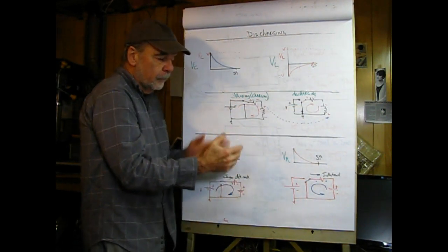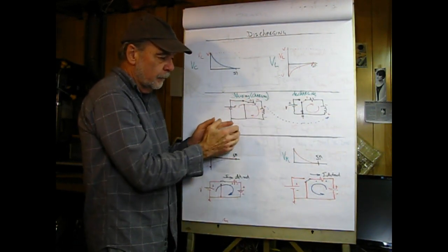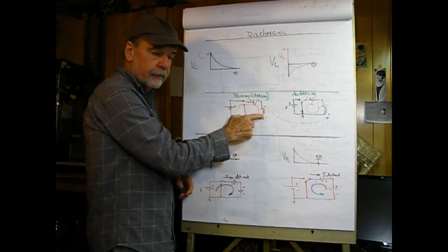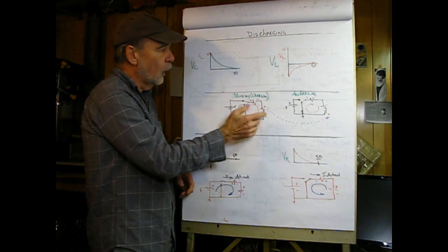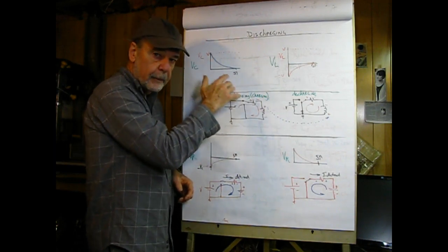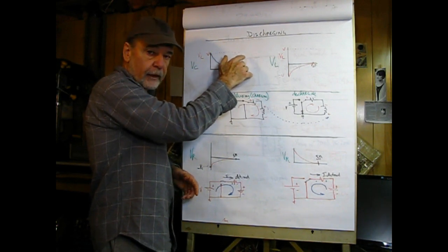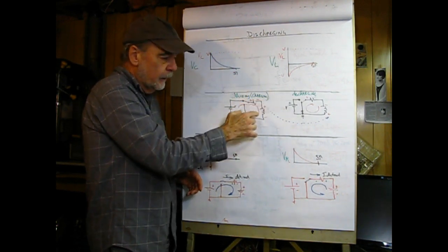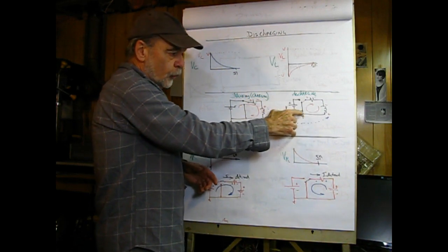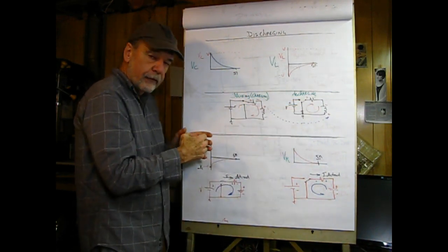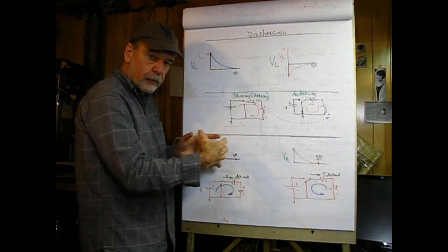Now when you think about it, when we charged the inductor, the field was growing, and it induced a counter EMF in the inductor, which gave rise to the exponential shape of that, starting out at our 10 volts for finding VL and decaying. Now when the switch is flipped in the opposite direction, where it has a discharge path, that field is no longer growing, but it's collapsing.